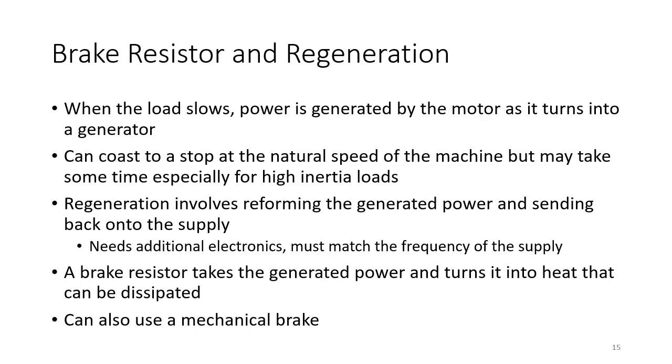Another option, of course, is to use a mechanical brake, but if we use a mechanical brake, then again we've got extra components, and now you might have brake pads. Those brake pads may need to be maintained. And there's still a little bit of extra electronics, but not as much. But you need extra electronics to actually control that mechanical brake. So a brake resistor is a common way that's relatively low cost, straightforward to implement, and it's a way of making sure that the system slows down faster than it would if you just left it to it.